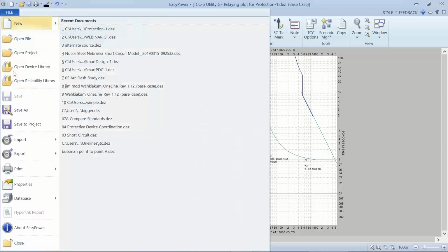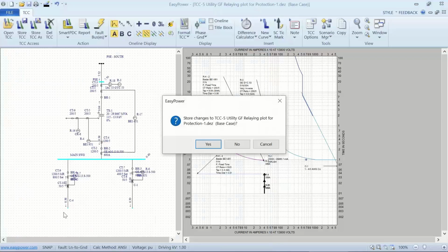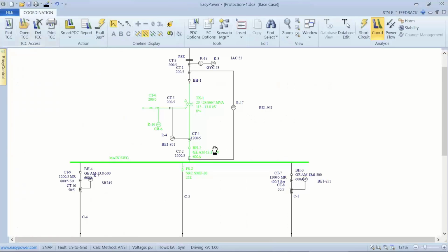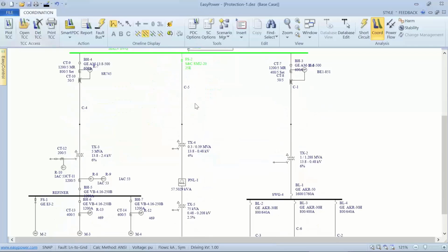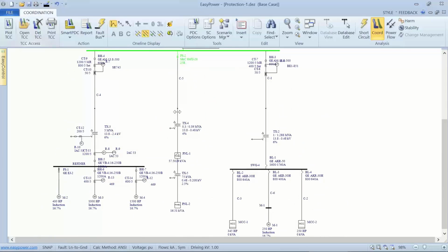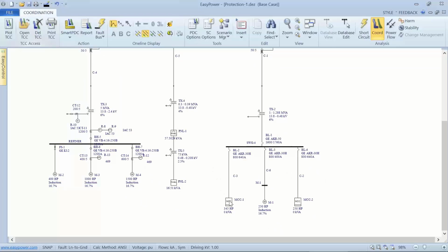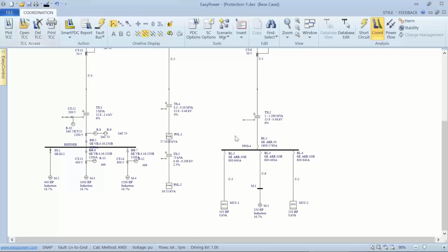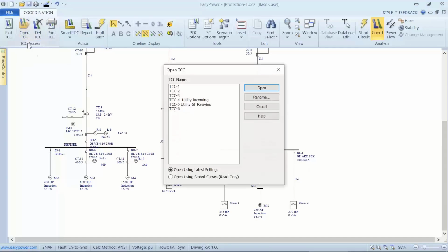There is, in this particular example, a good discussion or presentation on coordination from breakers. You can coordinate against the breakers with the TCC curve in panels and motor control centers, and feeder breakers both inside the motor control center and the mains upside. And so for those kind of coordinations, I think we even have a plot.